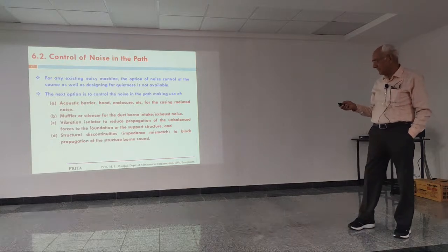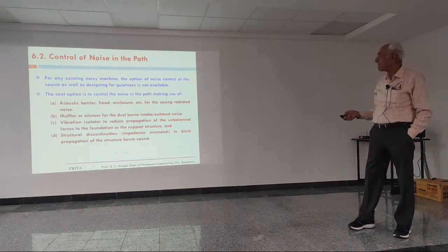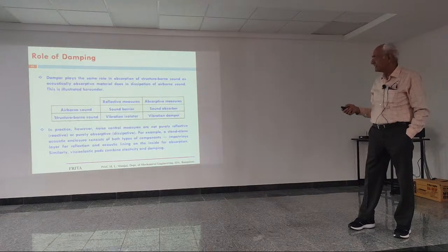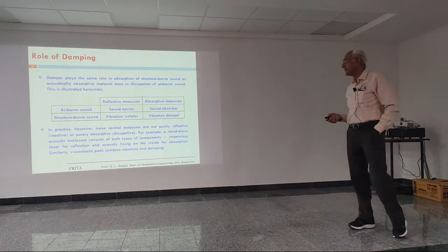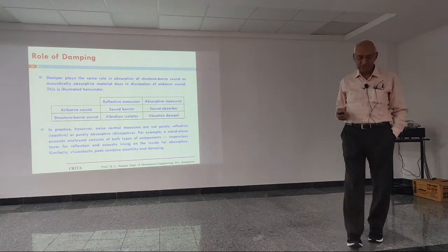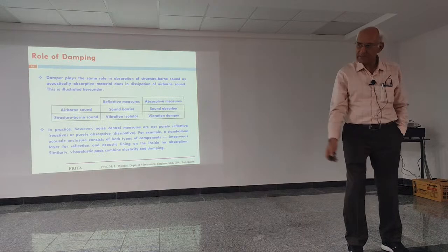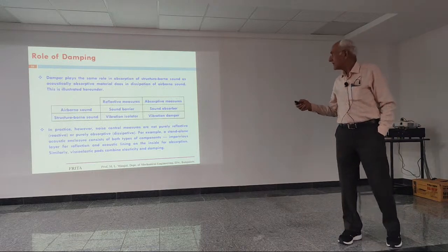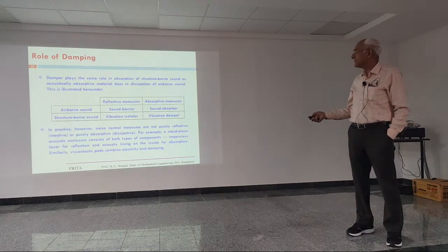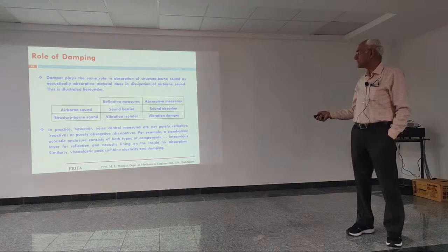Okay. This is regarding the past. Now, the role of damping, particularly when you come to structure-borne sound, or the noise that is produced as waves in the structures. Now, a damper plays the same role in absorption of structure-borne sound as acoustically absorbing materials do in dissipation of airborne sound.